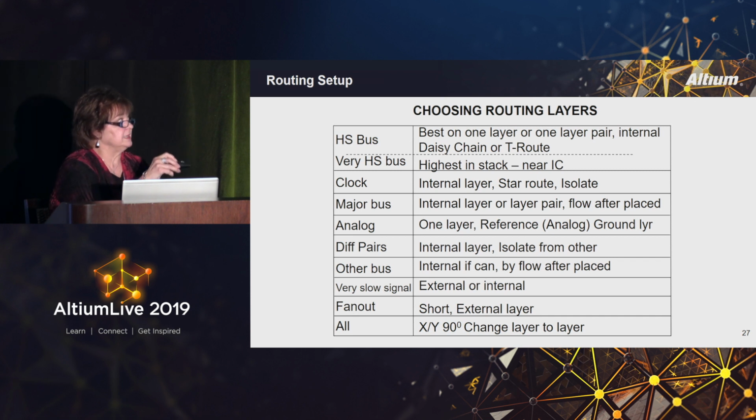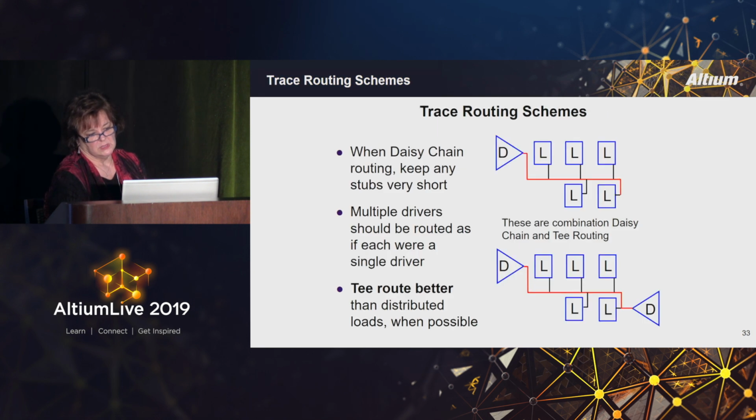This is a guideline. It certainly does not have to be done this way. Can you put high-speed signals on an outer layer? Sure you can, but will they perform the way you want? That's the question you have to ask. Where was I?